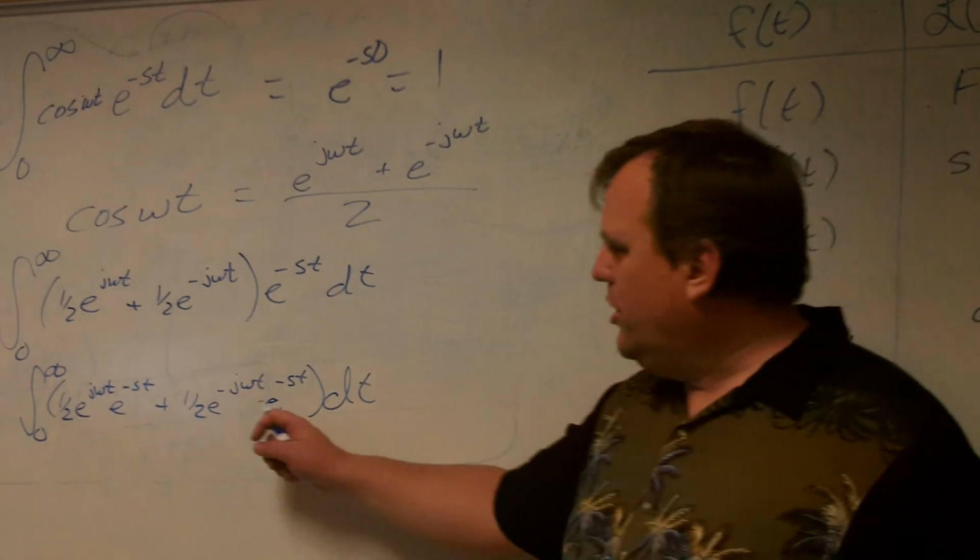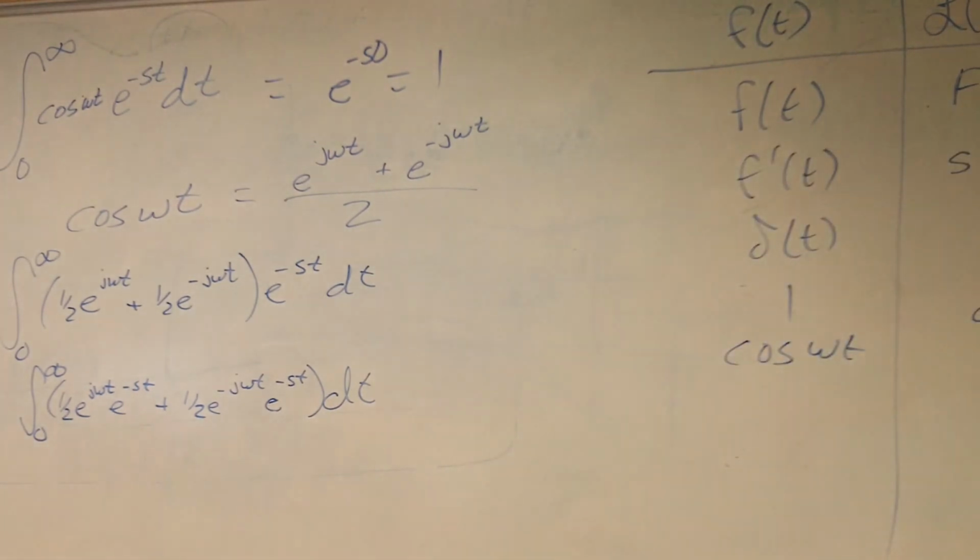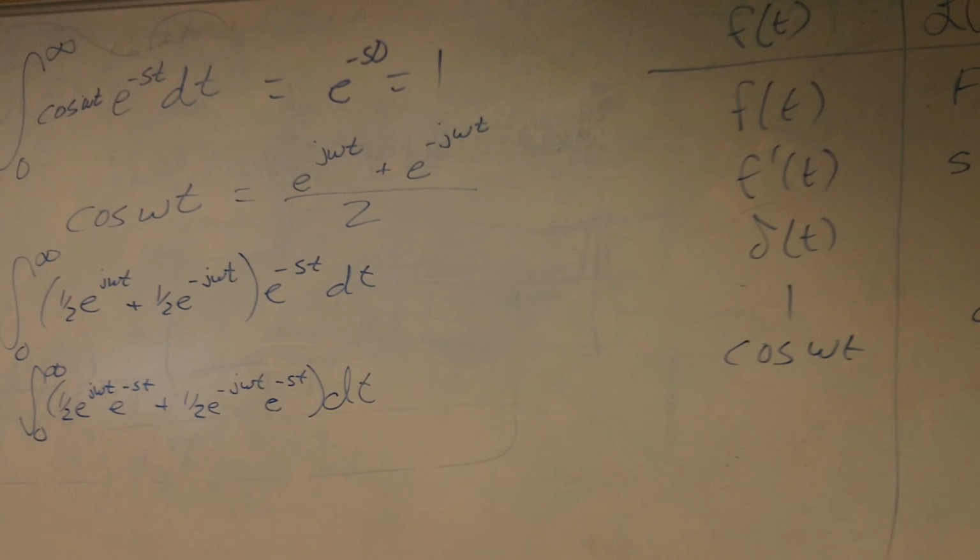The right one, the only difference is instead of j omega, it's got minus j omega. That's just a difference in sign. So what you'll get for the other side is j omega just gets negated. Doesn't the infinity change too? You go to a positive infinity instead? You're right, but it's not the oscillation that's killing it. It's this that has the real part. It's the damping that is causing it to go to 0, and I didn't change the damping. You changed the frequency of oscillation. It doesn't change anything. All it changes is the sign.